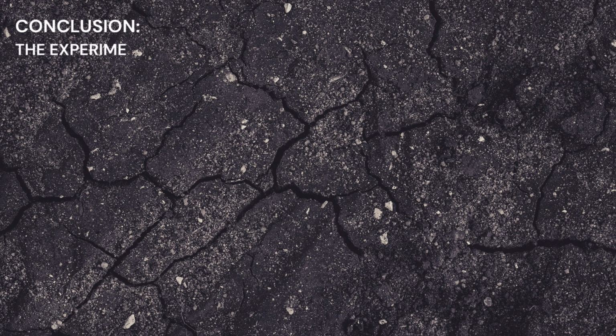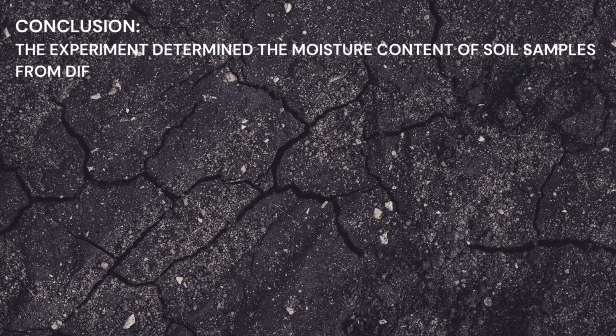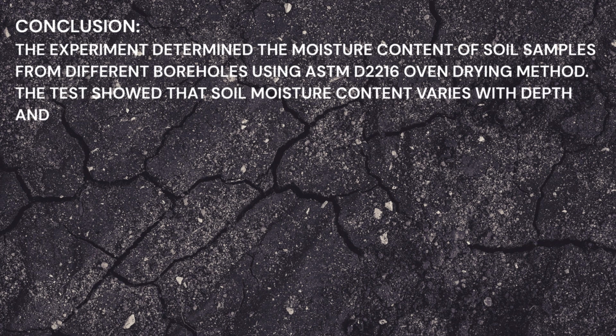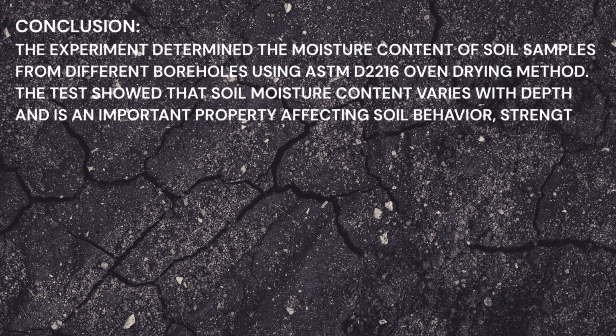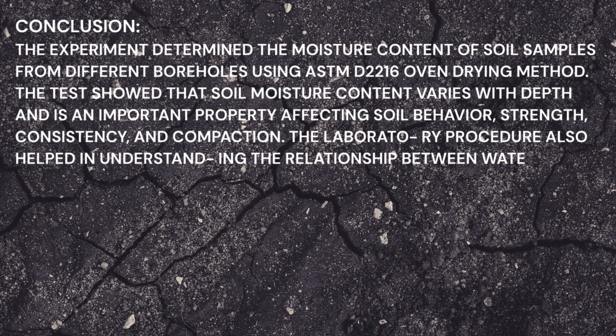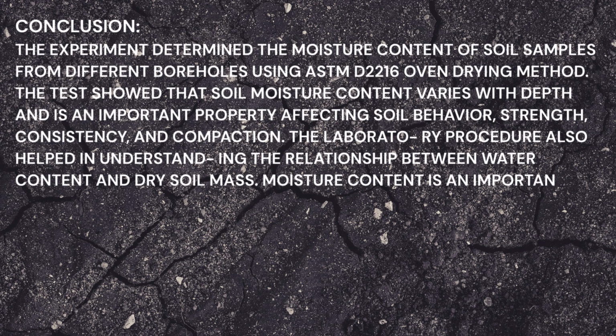Conclusion. The experiment determined the moisture content of soil samples from different boreholes using the ASTM D2216 oven drying method. The test showed that soil moisture content varies with depth and is an important property affecting soil behavior, strength, consistency, and compaction. The procedure also helped in understanding the relationship between water content and dry soil mass.